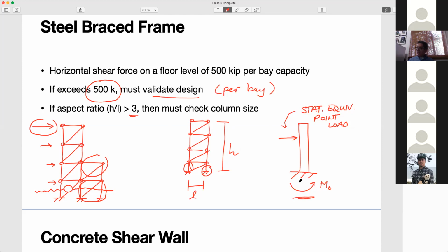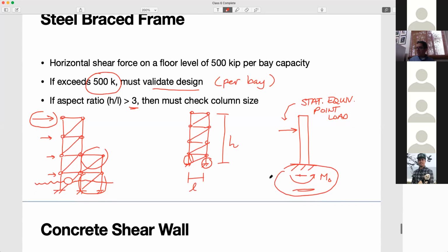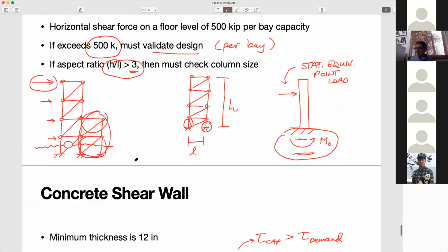And so not only do you have a base shear down below, but you then have a very large bending moment that would show up. So we use a beam analogy to get us right in terms of the aspect ratio. That's why, as I went down here, I added more frames down there, to help with the aspect ratio.